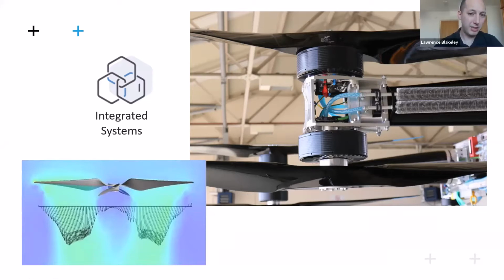And what you'll see is there's quite a dead patch underneath the rotor at the hub, where you actually don't get very much airflow. So it was really important for these cooling pipes to be running along the length of the arms, because we really take credit of the fast moving airflow. And that's what I mean when we're having to couple the different systems together quite heavily to develop this capability.